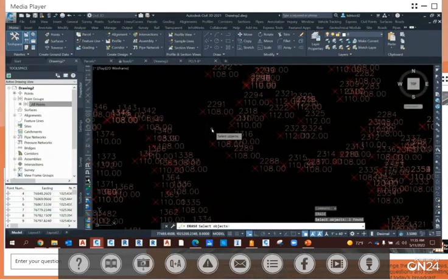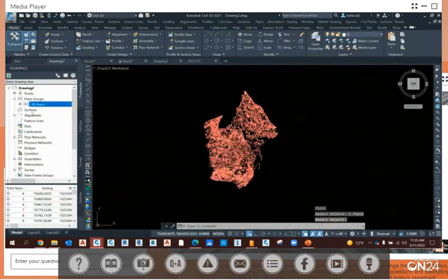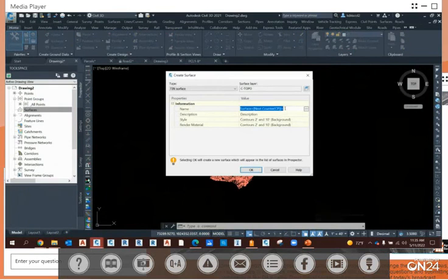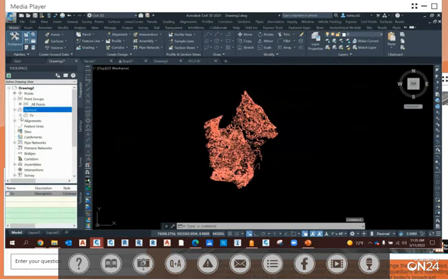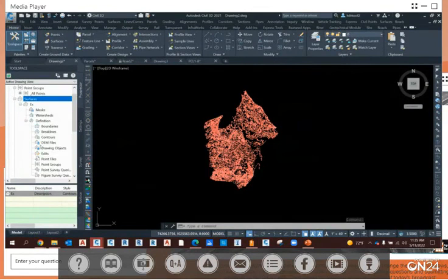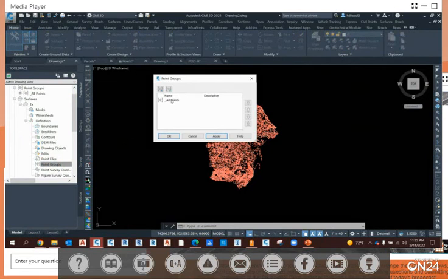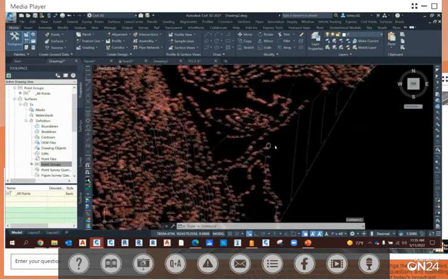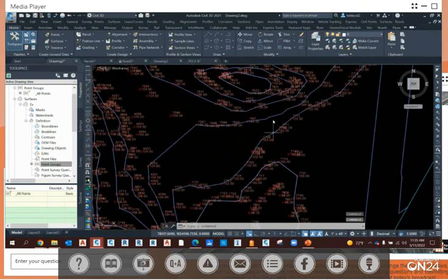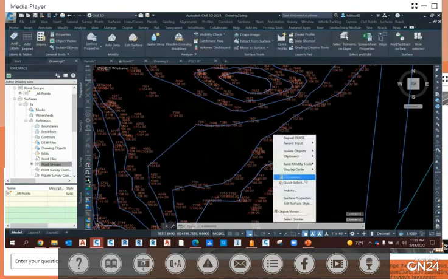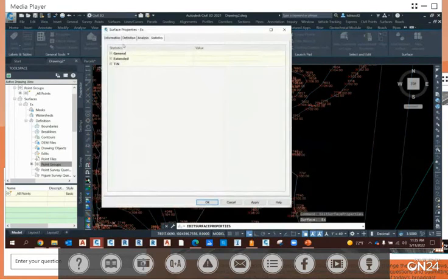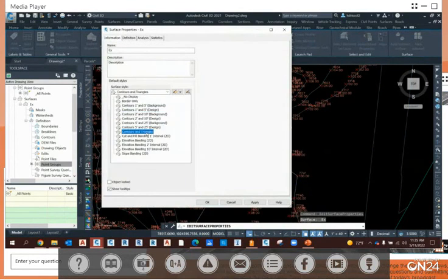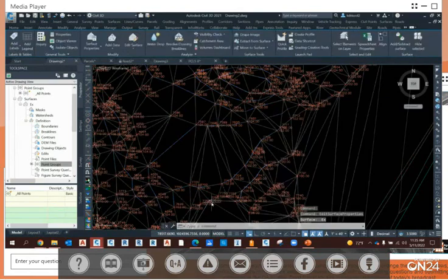And again, it's about time savings. In Civil3D, we want to just be able to create a surface, from our surface, all that surface existing ground, from that existing ground surface. In terms of time saving, with AutoCAD, I've created one triangle, no contour. In Civil3D, I just add a point group. I select OK. I've got my contours. Not only do I have my contours, but if I pick on my surface, because this is a model that's been built, my triangles are created automatically.